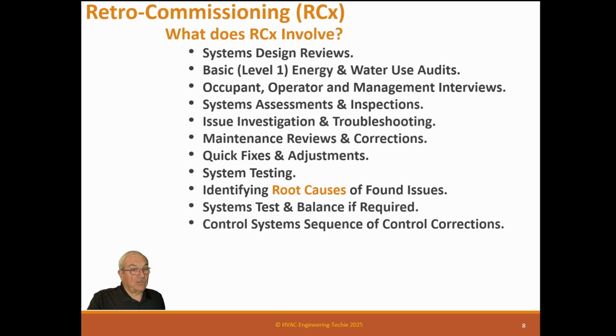Control system sequence and control corrections. Here's another deal. If you're not a control person and you don't understand sequences, someone on your team needs to be, because this is the second area where I guarantee you there will be problems. Not because the original program may not be any good. It might not be good, but even if it is good, it has had a lot of people working on it over the years, and it may have been changed to incorrect parameters, or that sequence may have been blown out altogether. So you have to have a control person on it.